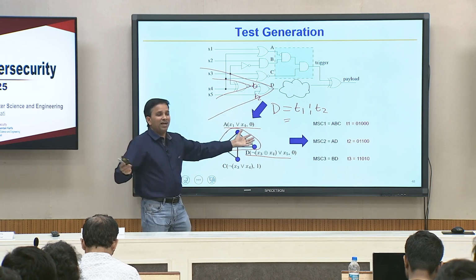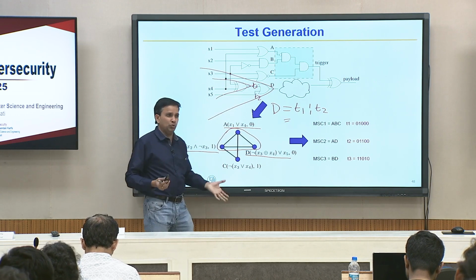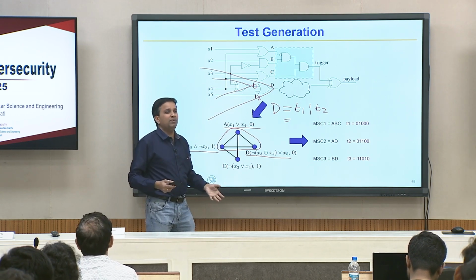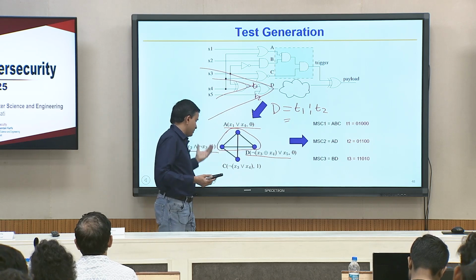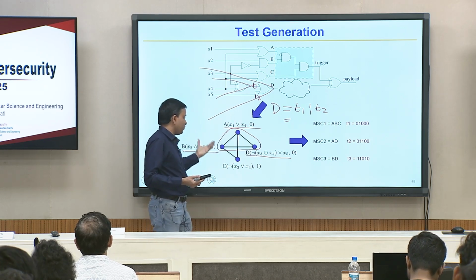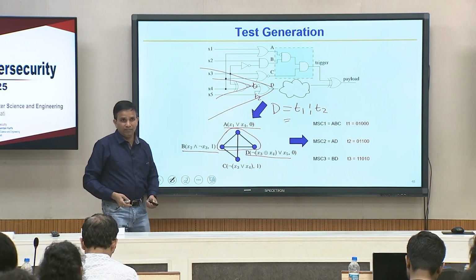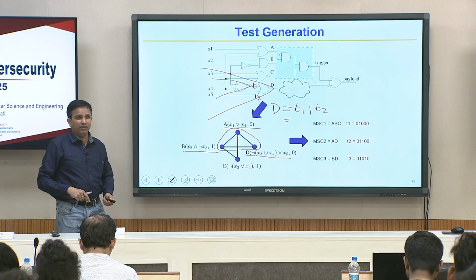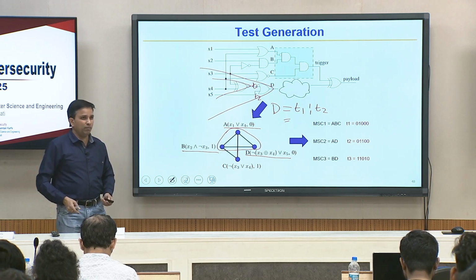When you have real hundreds and thousands of gates, this expression is going to be huge, and giving it to any reasonable SAT solver, handling all these conjunctive normal form expressions and their intersection, that SAT solver will fail, even if it is satisfiable. Even finding the time to tell you it is satisfiable is going to be a problem.